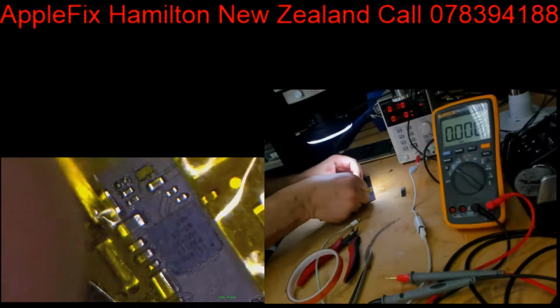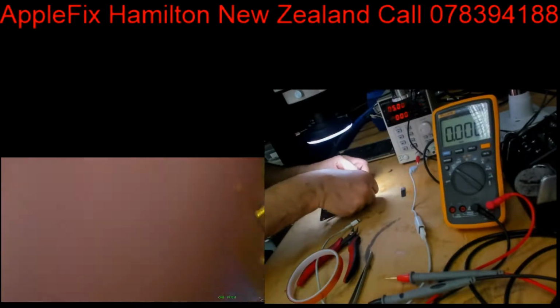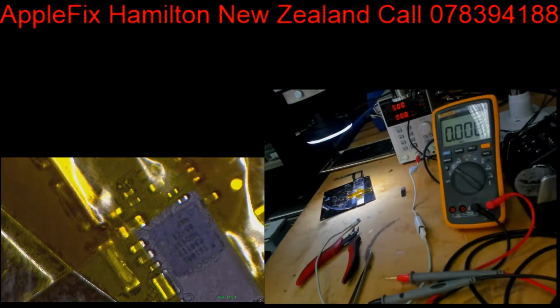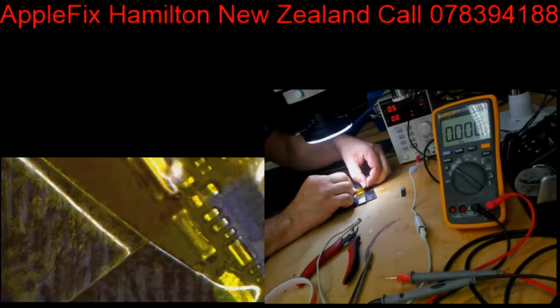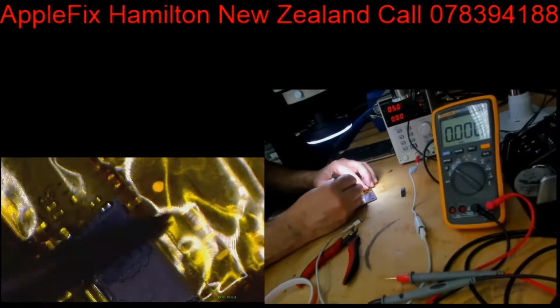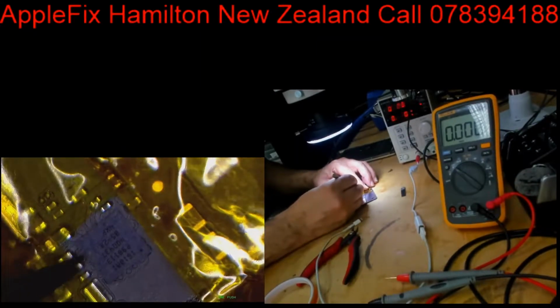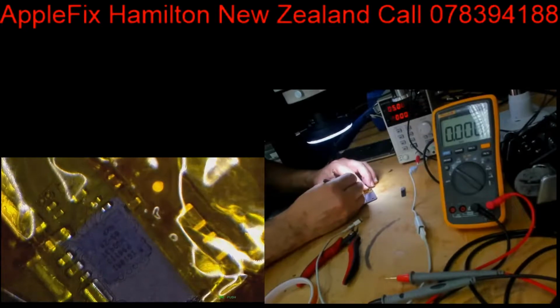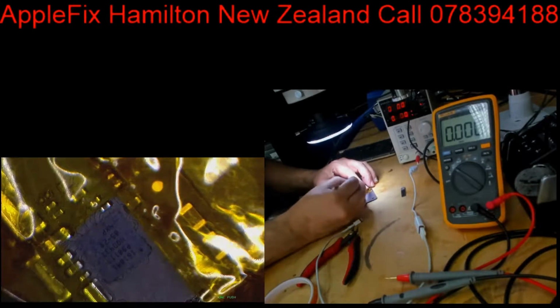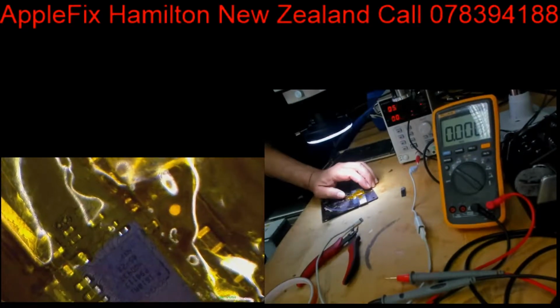U2 IC is one of the easiest to remove, for me at least. I find it very easy. So I will just mark it, this is where the orientation is. I will bring it to the microscope so that you can see.